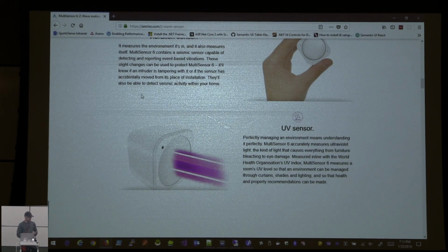But I've got some GE switches. I'm trying to remember, they go by another name too, or they're cross-marketed with another brand. They're the exact same switch, just different name on it. And they work just fine. They handle more amperage than most of them. Most of them are 15 amp, and those are 20 amp, the GE ones. And then one of them has a dimmer built in, which is usually extra.